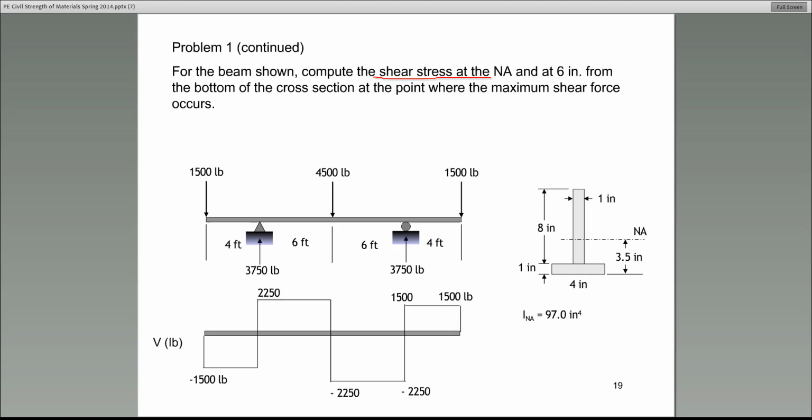Okay, guys. Now that I have your attention, let me explain. The answer is it depends. And Arash actually is giving me the right answer. He says you decide what the width is by looking at the section in which you're doing the calculation. He's absolutely correct. So what we use as B, it depends on where along the cross-section you are evaluating the shear stress. And that's what Arash is saying.